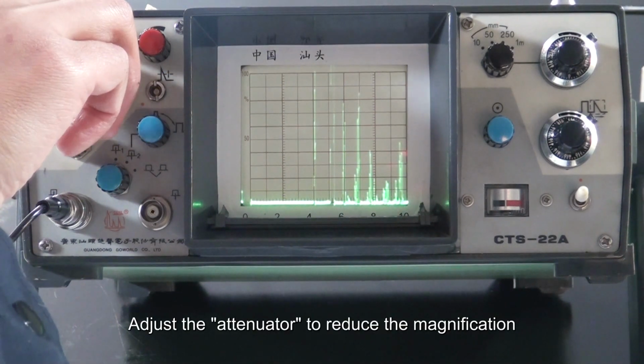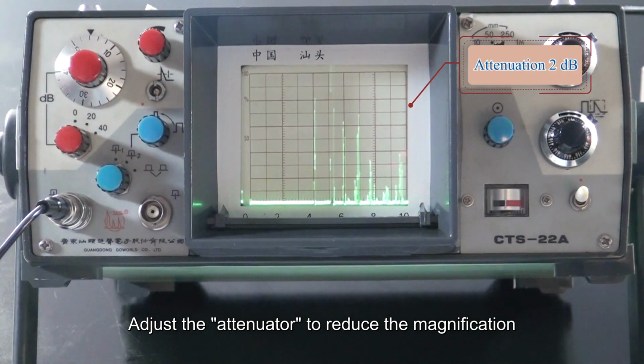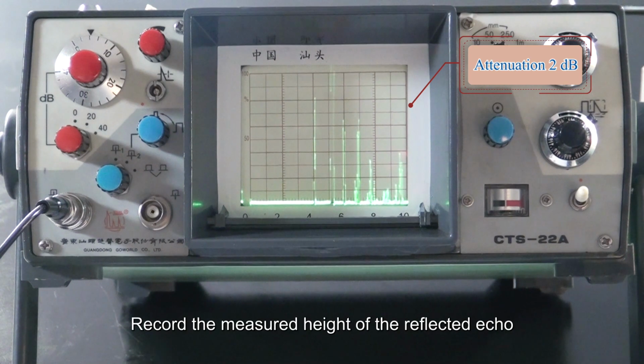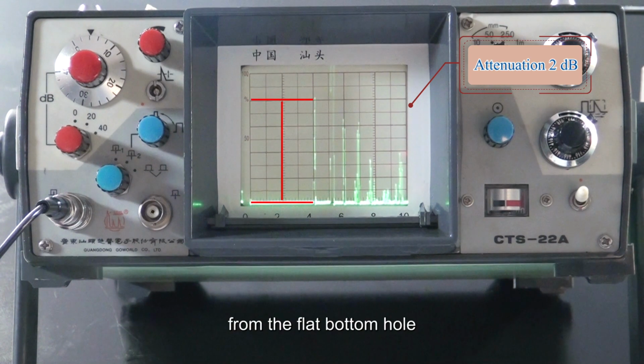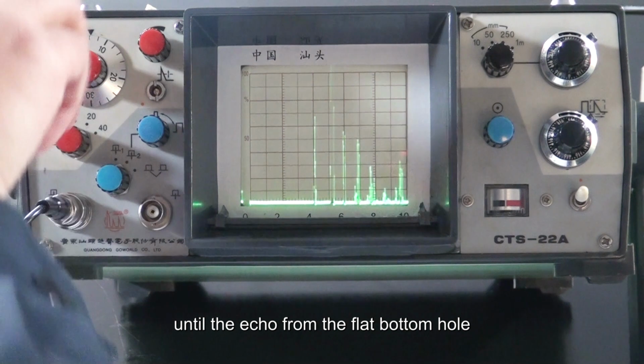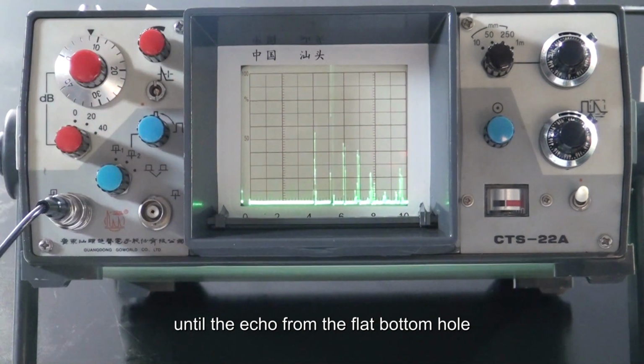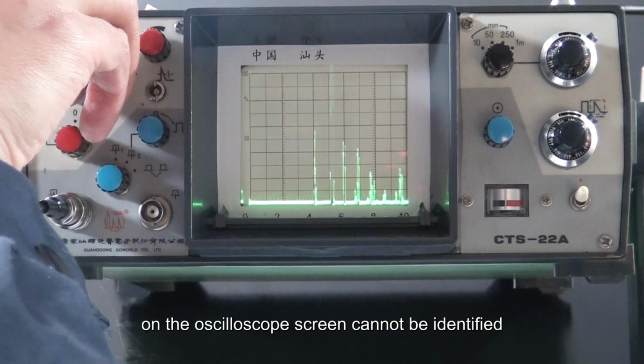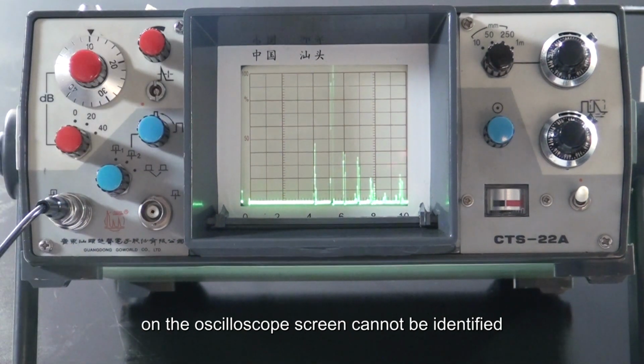Adjust the attenuator to reduce the magnification by 2 decibels each time. Record the measured height of the reflected echo from the flat bottom hole after every 2 decibel reduction, until the echo from the flat bottom hole on the oscilloscope screen cannot be identified.